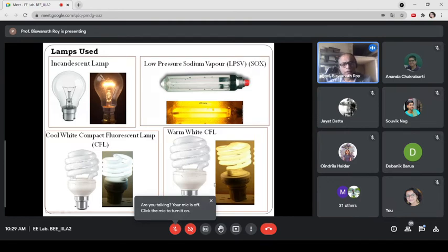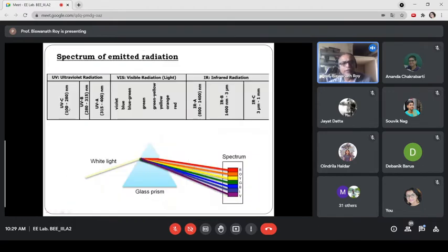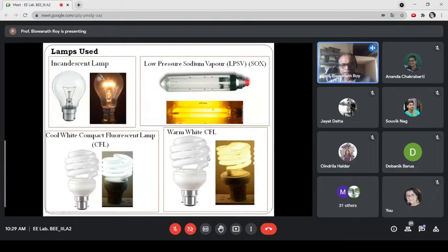One is electroluminescence, where the low pressure mercury vapor lamp emits radiation in the UVC region, and then UVC radiation excites the phosphor coating, which is purposefully coated on the inside of the discharge tube. So that the excited phosphor emits visible radiation, the photoluminescence.